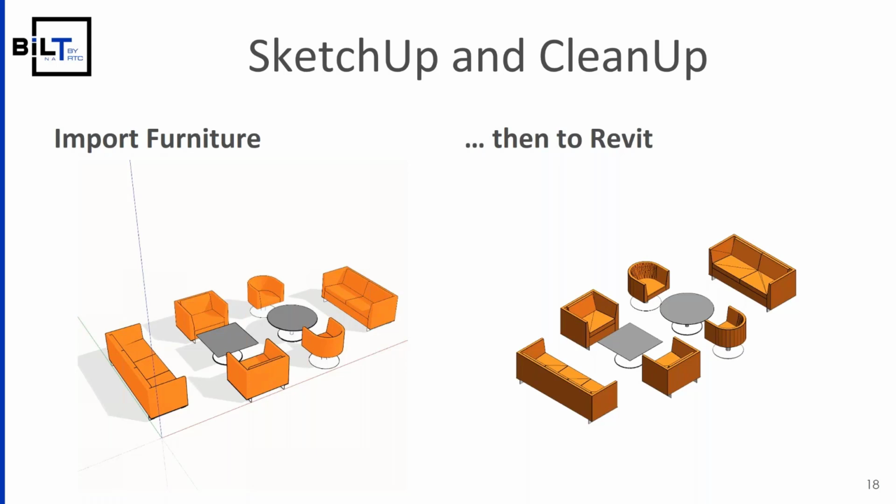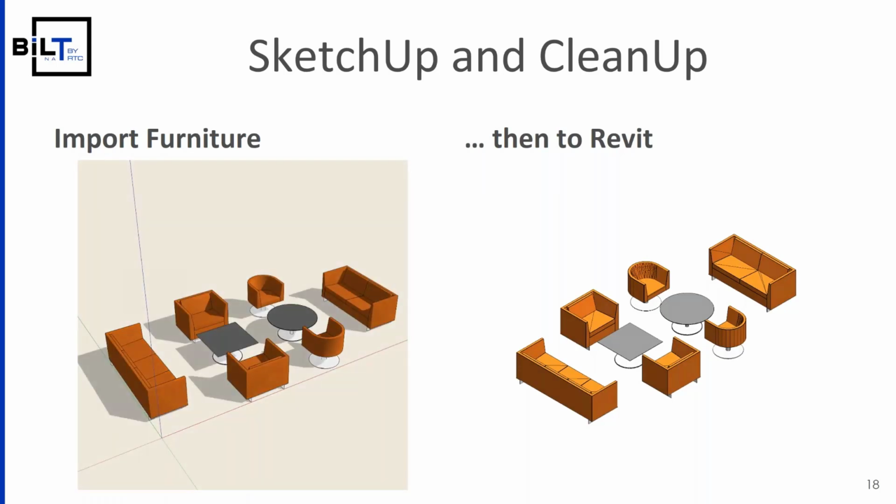This is just a quick slide showing the SketchUp workflow. So on the left is some stuff I got from the SketchUp warehouse, and then importing to FormIt, you can see it's incredibly high fidelity. You get the materials, the geometry, and other things like that. You can now pop that into Revit also, and you'll get the materials that come across. So you've got furniture, things like that, that you can pull off the SketchUp warehouse into Revit.